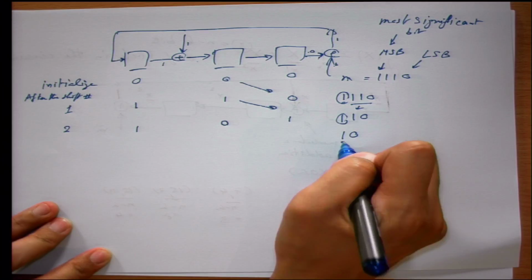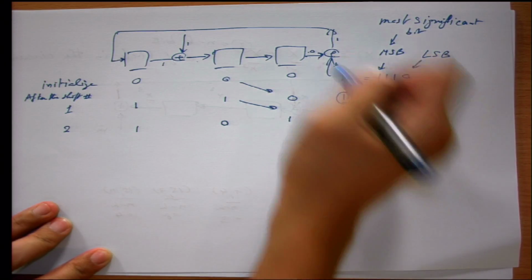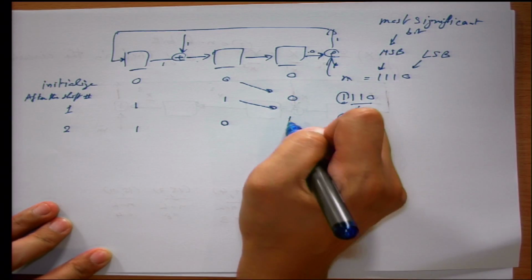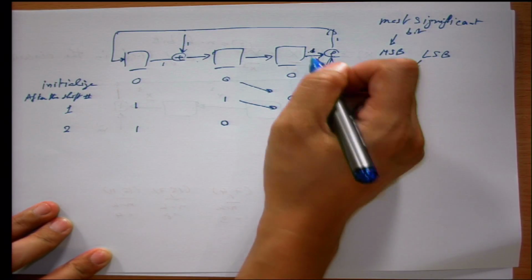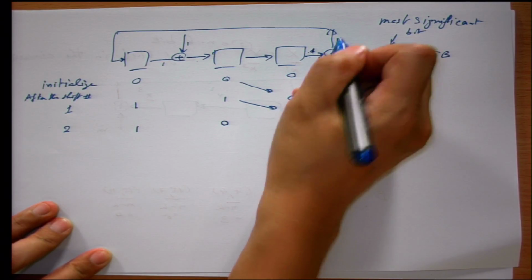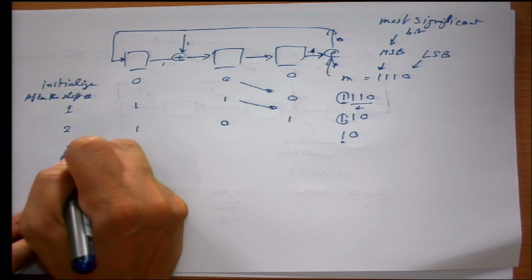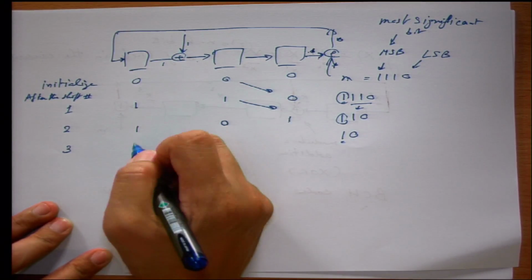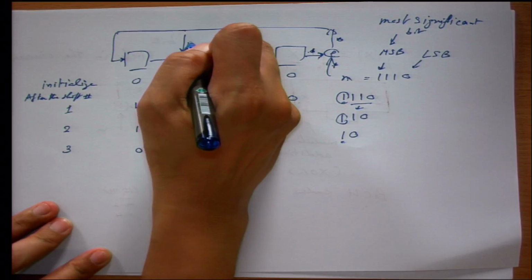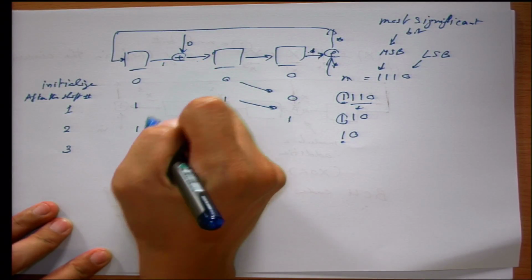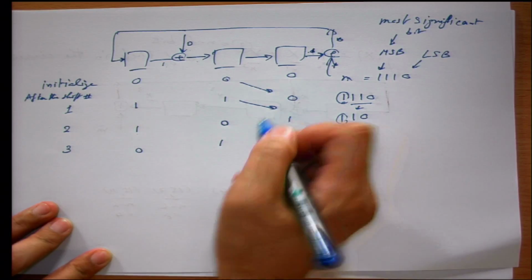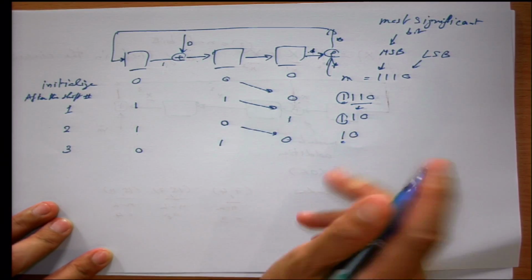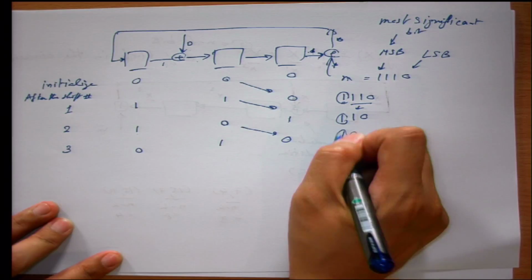So this bit gets in, so you have 1 getting in here, and in the register, this is 1. So 1 plus 1 is 0, so you shift out as 0. After the third shift, you have 0 here, and 0 coming in here. So 1 coming out plus 0, you get 1. This is shifted like this, so you get 0. This one has already gotten in.